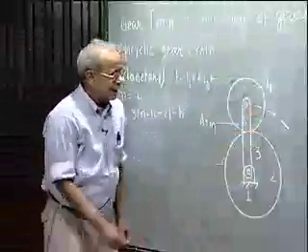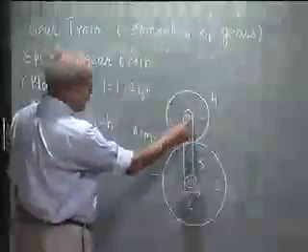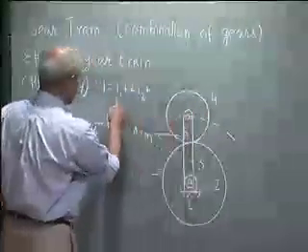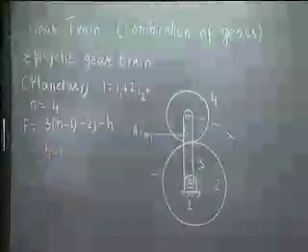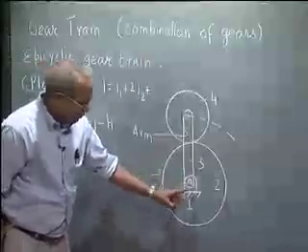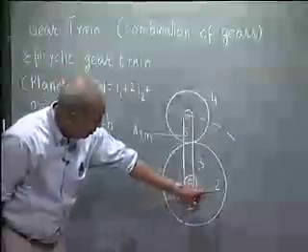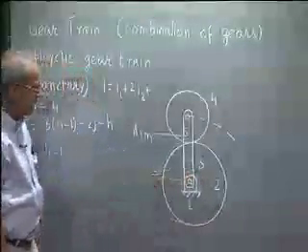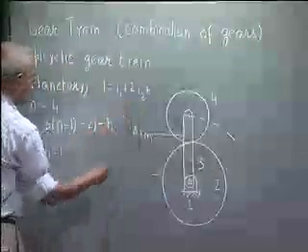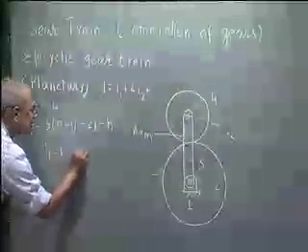Now here, there is a revolute pair between the arm and gear 4, so j1 is 1. Here is a revolute pair, but that connects 3 links, namely 1, 2 and 3. So this is a hinge of type j2. So j2 is also 1.